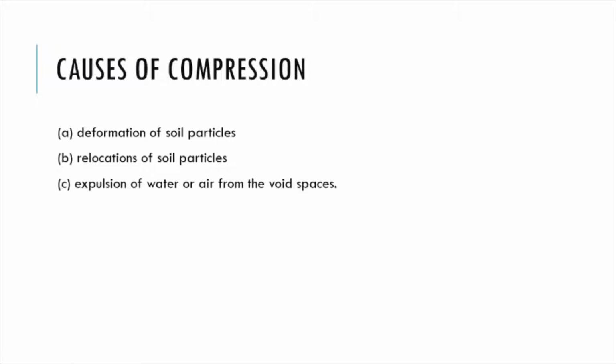And lastly, the expulsion of water or air from the void spaces, because when an additional load is applied, the tendency of the water or the air is to be expelled from the void spaces. Therefore, if the water is expelled, the void spaces will be lessened and therefore the compression or the settlement will occur.